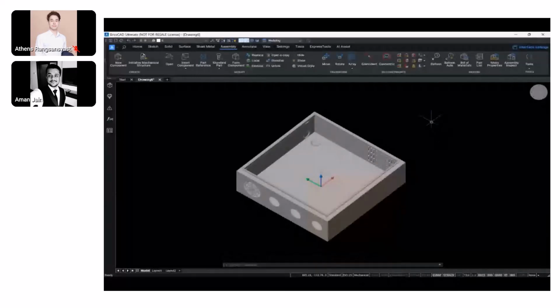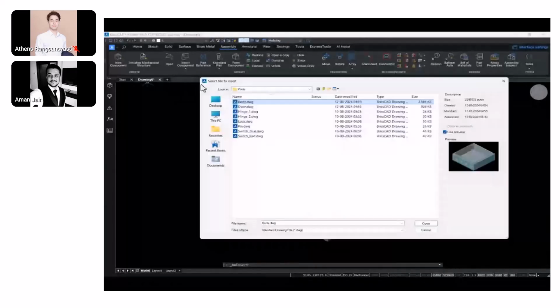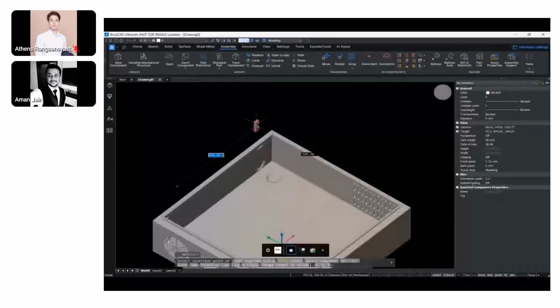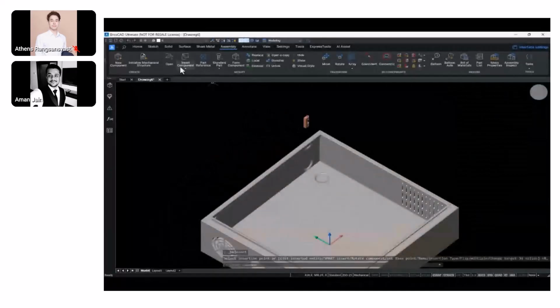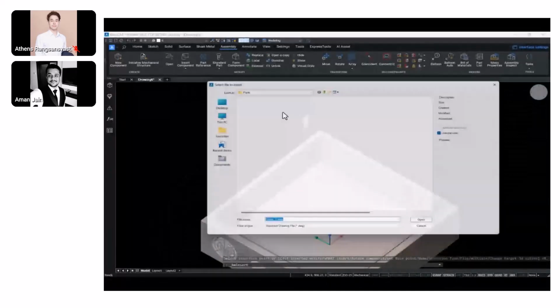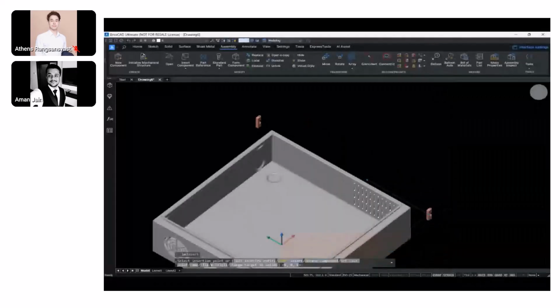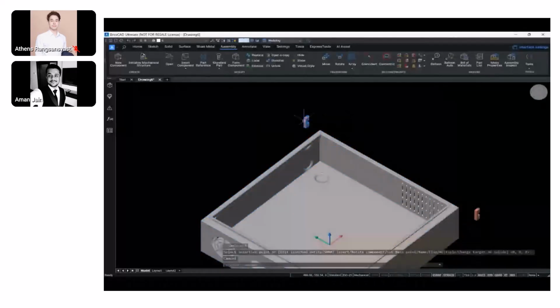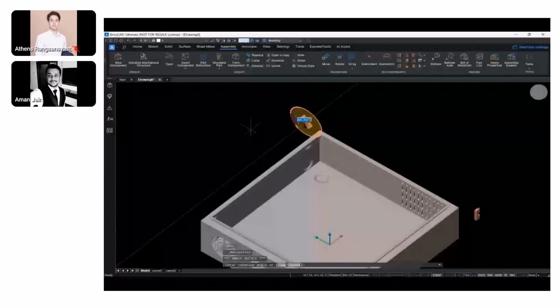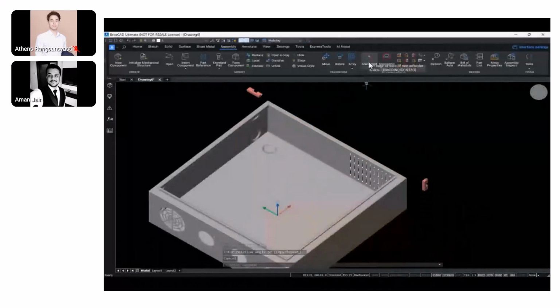So this is the main assembly, and inside the main assembly as well, we can insert components. So it need not be in a particular order like we saw with the door, where we need to create the sub-assembly first, and only then we'll be able to create the final assembly. It's not like that. These components, when we insert them, will be specific to this particular file. So any change across these hinges would be reflected in the main assembly file. Okay, that is how it works.